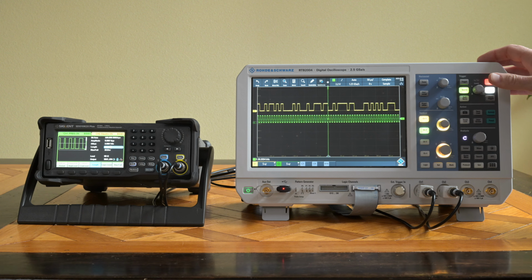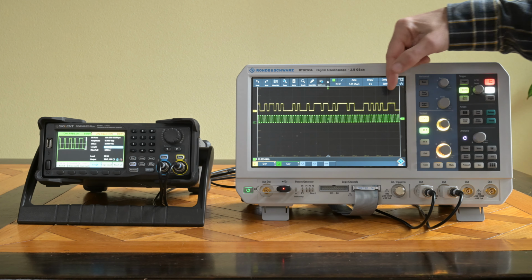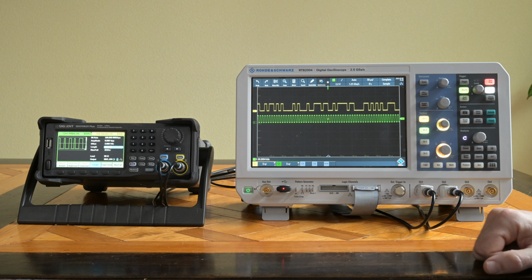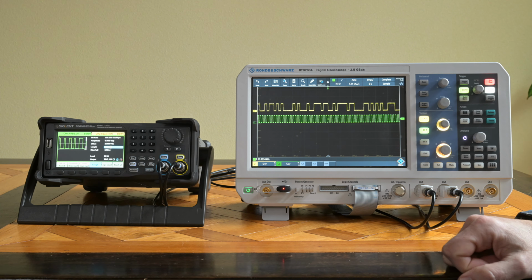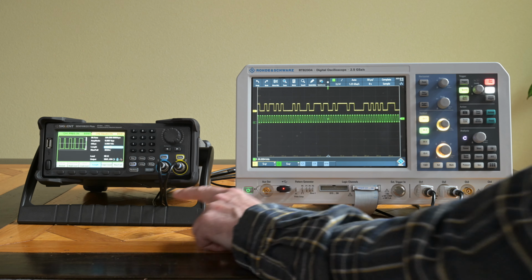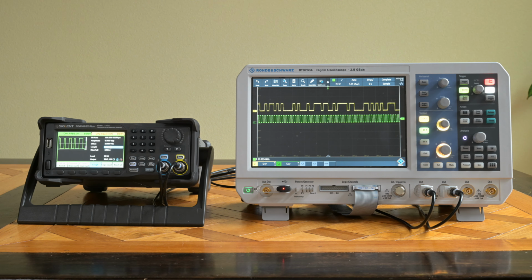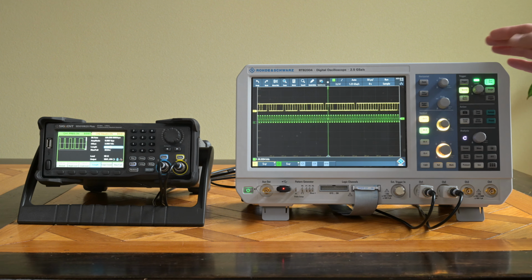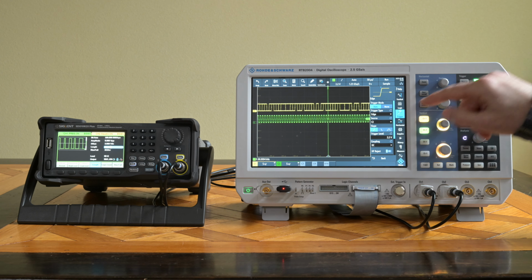If I stop the trigger for a second, I see a pattern, and that looks like something a PRBS pattern could have looked like. So there's nothing suspicious about that. So what can I test now? Well, basically I could try to see if it has exactly 9 ones in a row, because that is one of the things that we know a PN9 signal, which this one is currently generating, should have. Now there's a relatively easy way to do that, because we can use our trigger here.